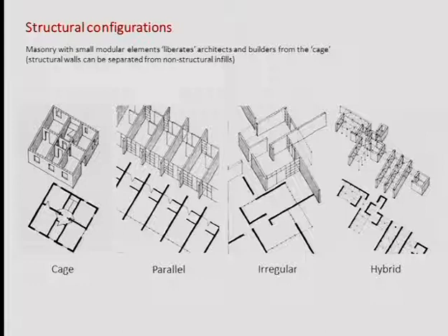You see structural walls in both directions so that it is laterally stable. But with structural masonry, you can actually do other things. You can have modular constructions so that you get this type of spines, and then you have infills, so that it is completely open, not structurally, and can be completely glass. Or there is another interesting use, again with elements in both directions so that they are laterally stable, but at the same time irregular.